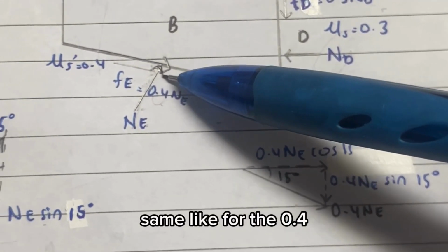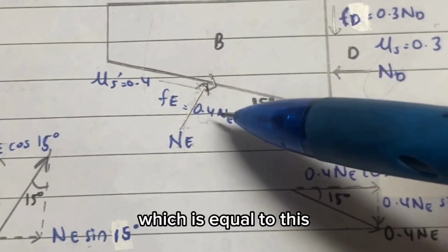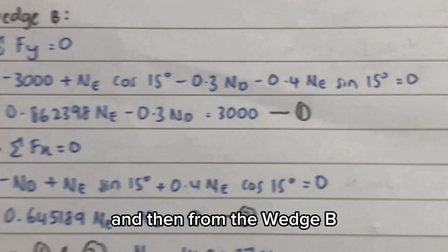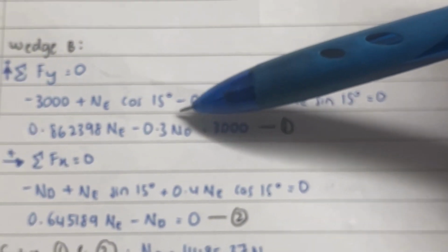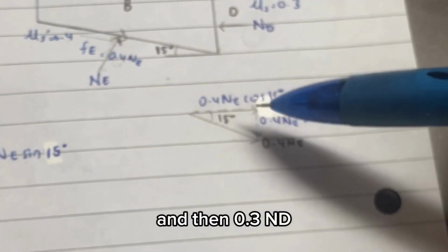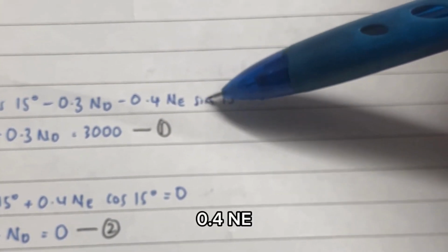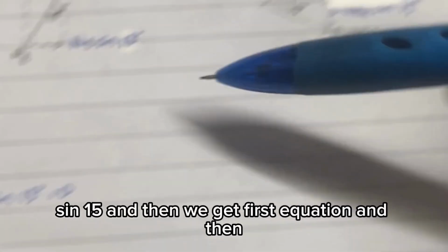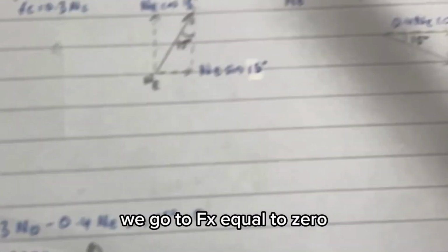Same for the 0.4 normal force E. Then from wedge B, for Fy equal to 0, this one acting downward is negative, and then Ne cos 15, then 0.3 ND friction force here, and 0.4 Ne sin 15. Then we get the first equation.